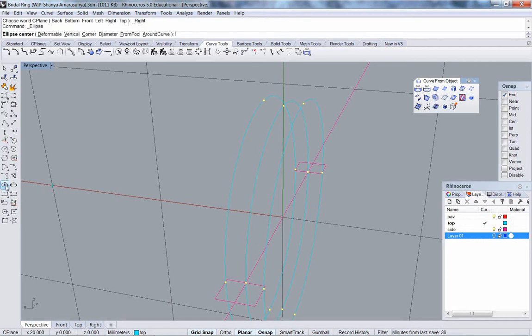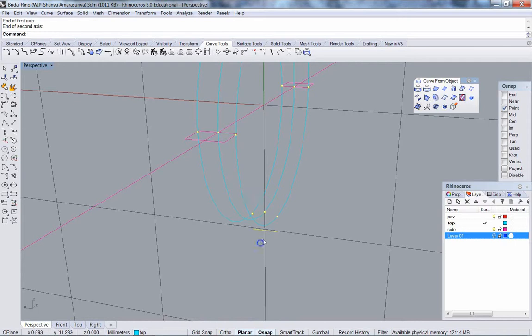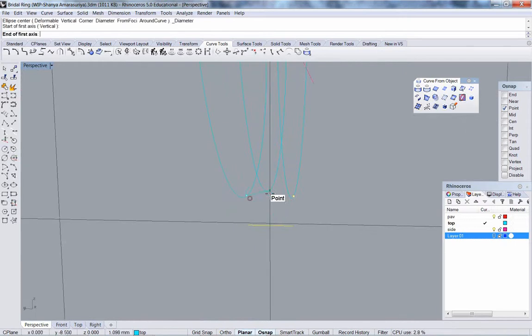Now you have to use an ellipse, otherwise you're going to have a corner. You're going to have a little bit of a corner anyway. There should be points in it. You can get rid of that with the blend surface, but at a certain point that becomes crazy. And there are other ways, but they get very difficult. You can do a circle tangent tangent.